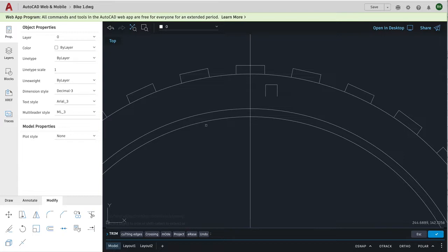So now what I need to do to make this look like it's fitting on the wheel, I'm going to rotate this a little bit. So notice I didn't draw it right here. I want this tread offset from these, so I've moved it over, but now I need to rotate it. So I'm going to choose my rotate, and that's under my modify menu. I'm going to select this object. There we go, and hit return.